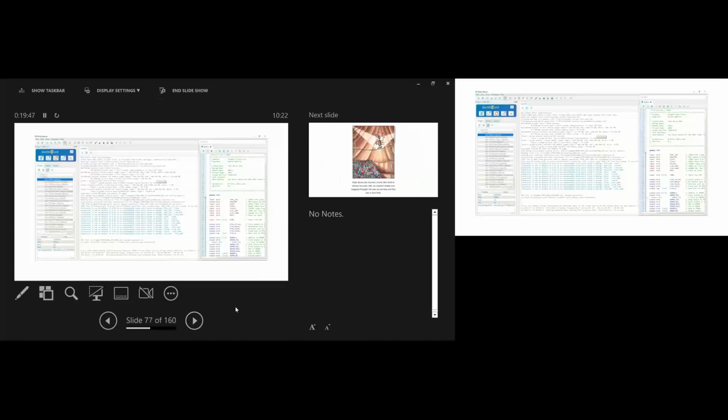Yeah, we had some more problems. After we got the initial code working, we then threw the entire few 100,000 lines of code at the devices, and of course it didn't work. The devices we were using only have 36 multipliers in. We need more than that. These are the hardware multipliers. But it's got a lot more logic in, and I thought the logic would take up the slack. It didn't. It burst the device.